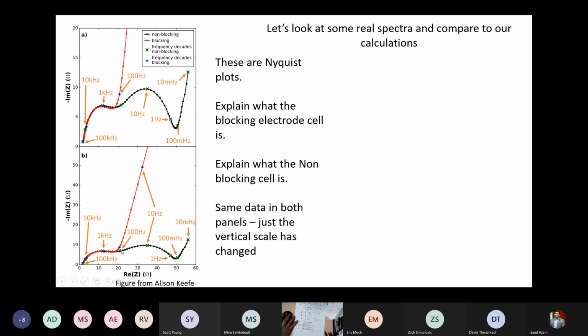The reason traditional impedance spectroscopers like to plot this way is because an RC parallel circuit gives an impedance spectrum that's an exact half of a circle, a semicircle, so that it means the height of the circle would be 1/2 of its width if this were a half of a circle being plotted. And this portion you can see goes up to about 8 or 9, but if you had to make an estimate of its width, you would say it's about 30. So this is a flattened semicircle.